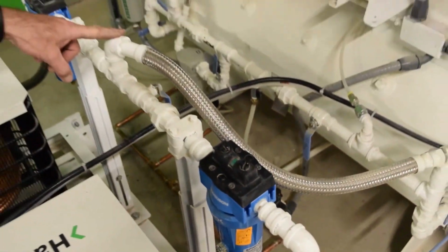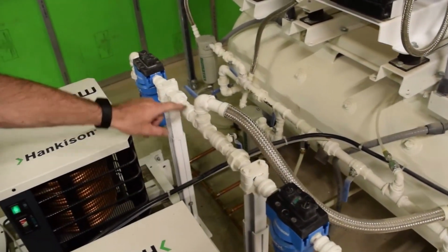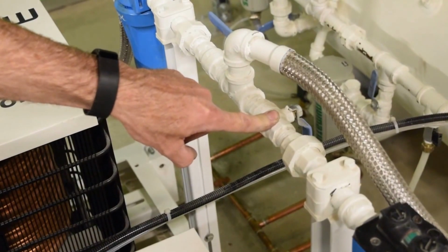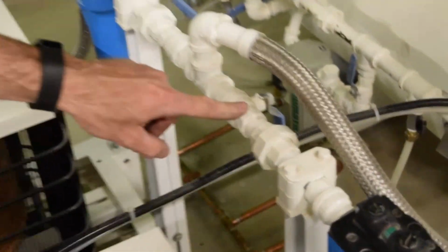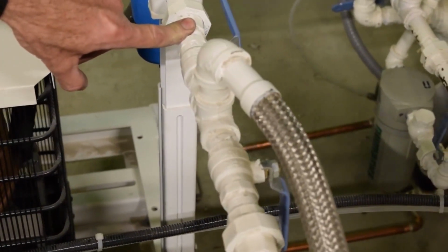Notice when the air comes away from the receiver tank, it comes into the dryer skid. One of these is valved on, the other one is valved off. You always want one on and one off, never both on or both off. Always one on and one off. Now you can alternate these annually, which would be the proper method.